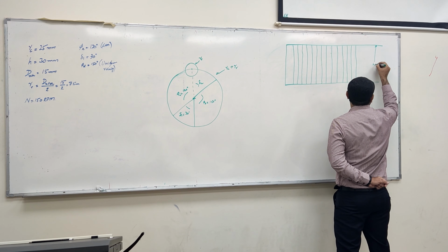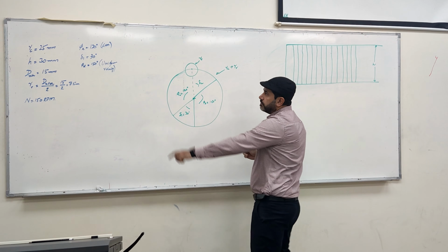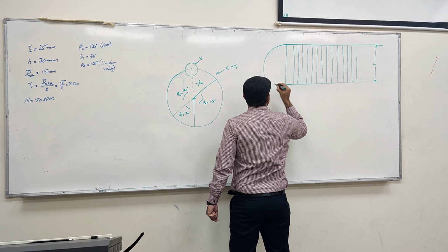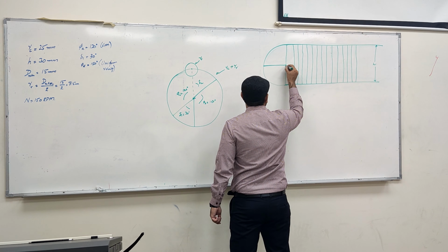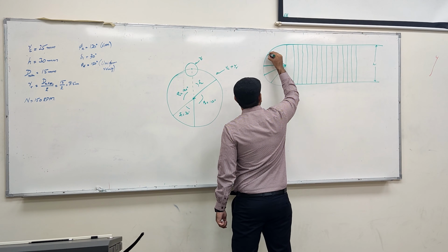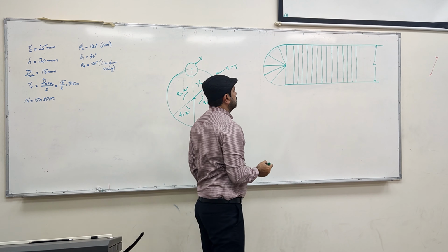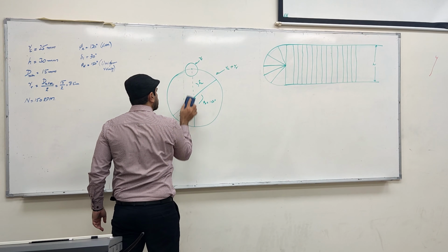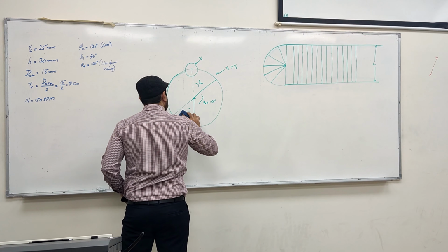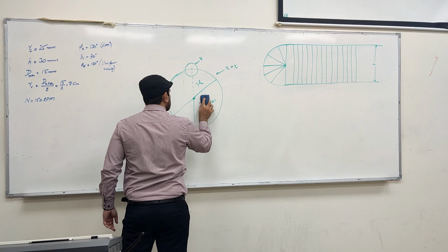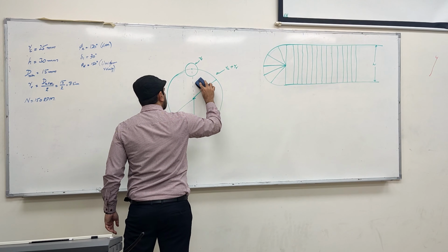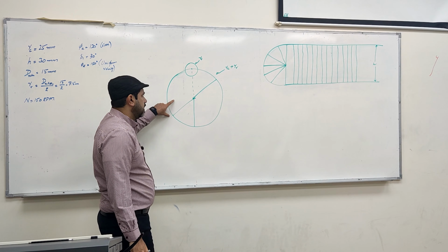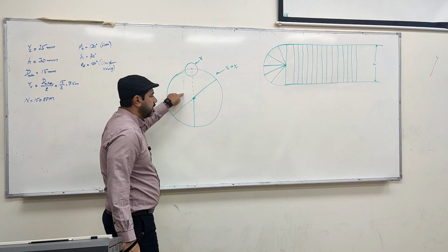This is the height. And since this one is simple harmonic motion, we need a circle. We'll draw the circle and divide it, let's say, into 6 parts. All right, now come back to this phi A part, which is over here, 120 degrees.